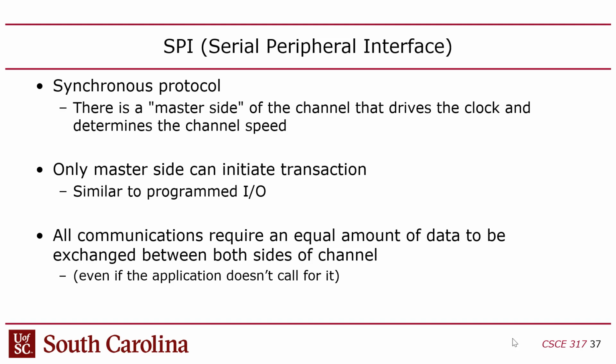Because the wires are usually different lengths, since you have to route them as a bus, there's also a lot of capacitance between the wires and crosstalk. It's kind of nasty, which is why PCI Express and DVI and HDMI and DisplayPort and SATA are all serial. Even the high-speed chip-to-chip buses have all gone serial, just because it's easier to deal with serial.